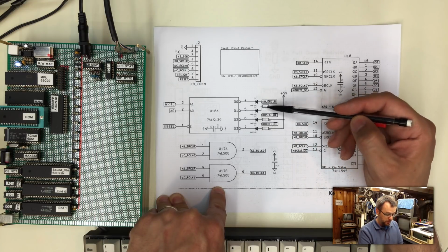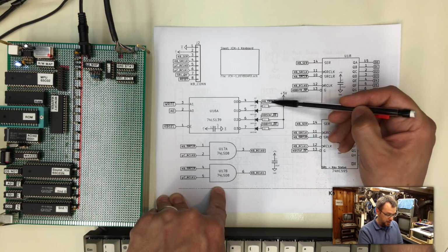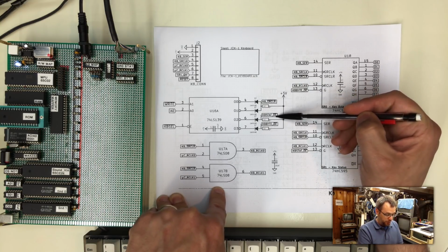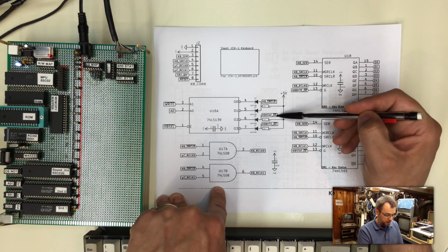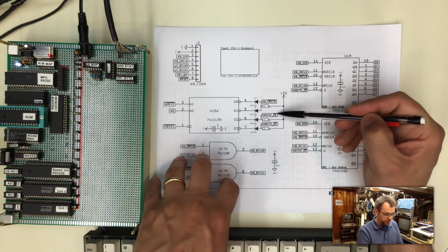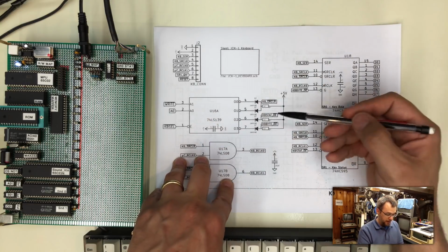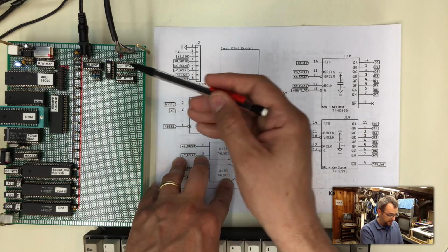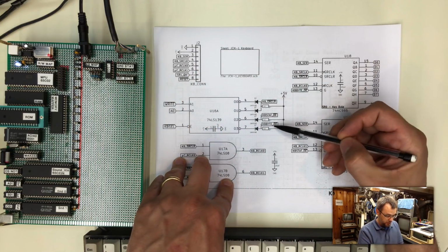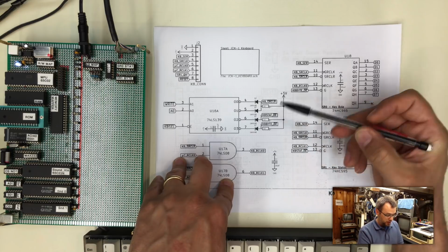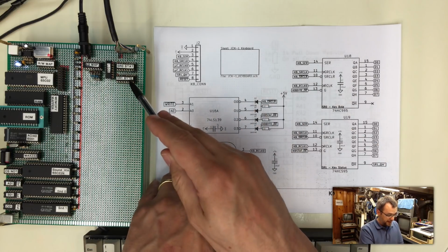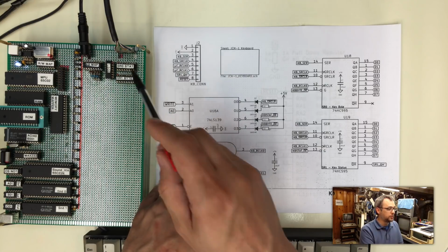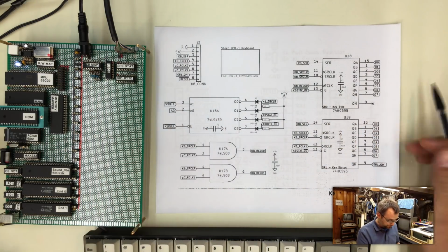and are combined together with the pull-up resistor and the diodes to either make our SR clear signal for clear both status registers, our KB status output enable register pin, so that if I'm reading the status, this will be active, and it'll activate that one, and this will put its data on the bus. And then the KB byte output enable. So if I'm reading the byte value, this will go low, select that, and the byte register will put its data onto the bus.